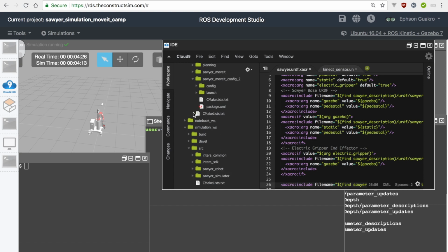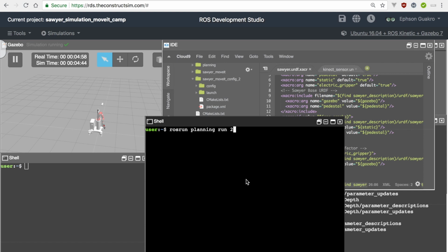So we're done with the robot description. We don't need that package anymore. But remember, first things first, what we have to do is enable the actuator joints for the robot and then get the joint trajectory action server up and running. Remember, you have to do this to get the planning and then execution from MoveIt to be done correctly. So to do that, first we're going to source.